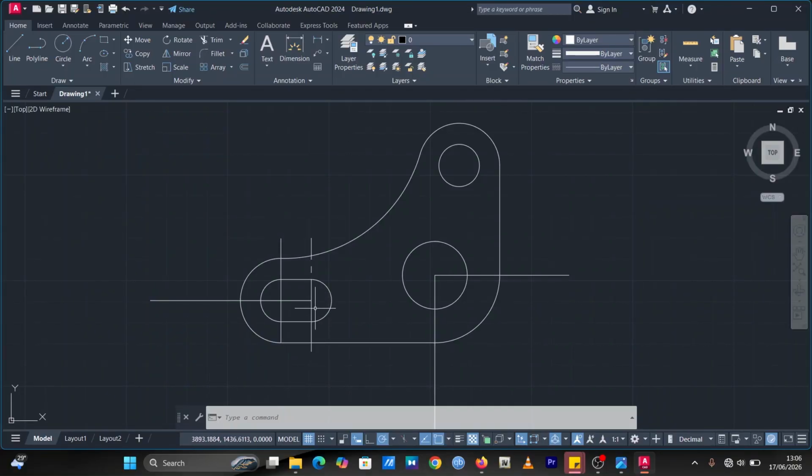Now we want to break this side too. So you can pick this, you come here again, you select the same center, and then you do it. But sometimes when you do it this way, it's not going to work. So most of the time I prefer you first delete these lines, and you delete this line also. And since you know this side is the center, we are going to draw a broken line to pass through the center, which was from here to here, the 15 millimeters.